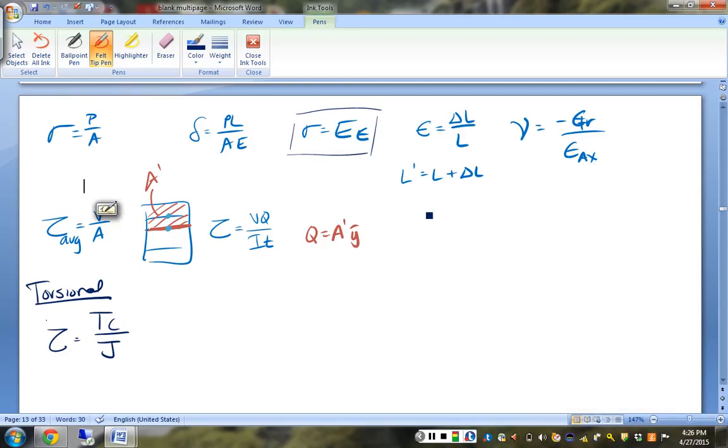There's also our shear stress and strain relationship. So this guy is your Young's modulus, that guy is your shear modulus. All material properties will be provided. Okay, so this is my shear stress. How about if I ask how much it twists? That's this guy's cousin, and it is TL over JG, and what's my symbol for that? It's a phi, the angle of twist.